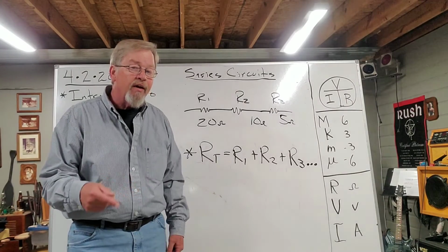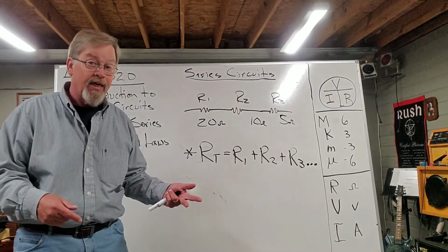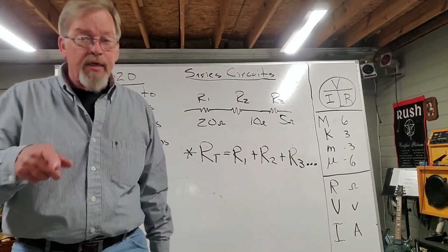This is end-to-end, called series. Current's the same, voltage divides, and you add up your resistors. Got that? Okay. See you in a minute.